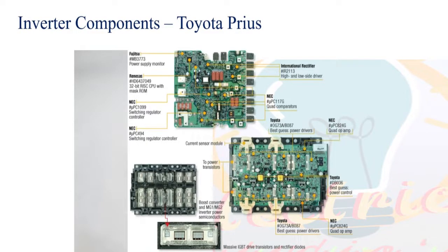In addition to that, your inverter also has certain sensors inside. When we talk about the inverter components, a very important thing is the sensor modules. You have current sensors, temperature sensors, and voltage sensing equipment as well. Why do we need current sensors? Quickly answer, please. Actually, what is the function this inverter is doing? It takes the input from the battery and converts the DC input into AC output, right? So when doing so, the inverter wants to know how much current is coming inside the inverter, how much current is going out of the inverter. Is it required or not?